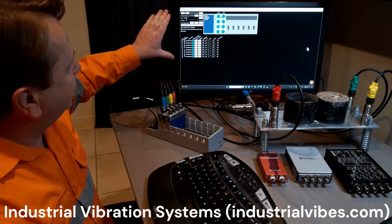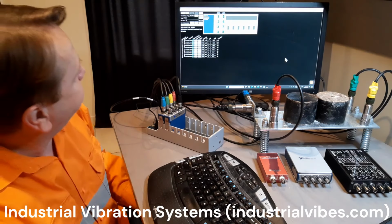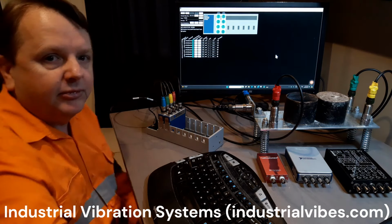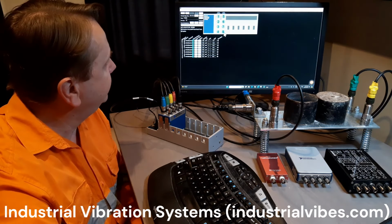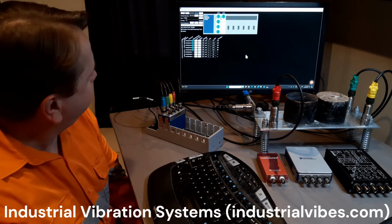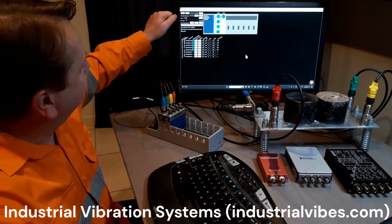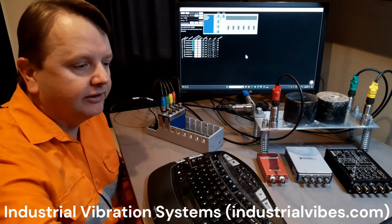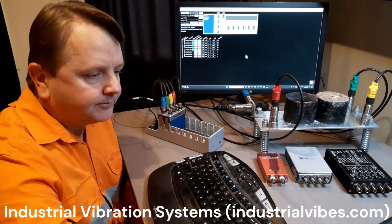Now you can see the software open in the background. That's all the default settings that you get when you open the software up. By default it's turned all 8 channels on and set them to IEPE mode. So I'll just turn off the last 3 channels because we're not going to use them. Okay, and we'll also stick with the default sample rate, which is the minimum for this hardware, which is a bit under 2 kilohertz, and that's more than enough for this because we're only looking at low frequencies.